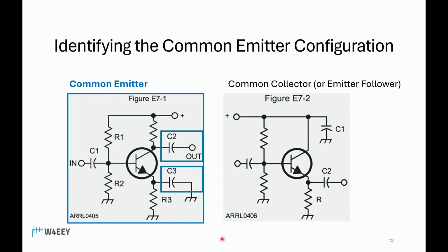In all cases, it won't appear this way in other circuits. You could figure out, well, what is the input? It's between the base and the emitter. What's the output? The output is actually common emitter. You'd think it would be on the emitter, but the way the circuit's configured, the emitter current actually appears over here.